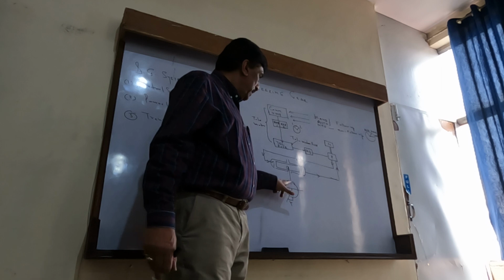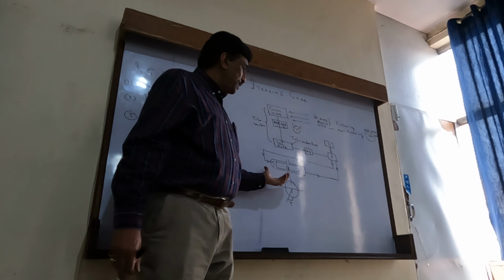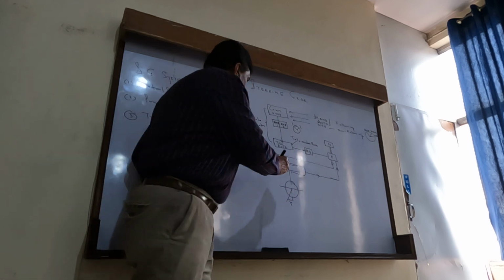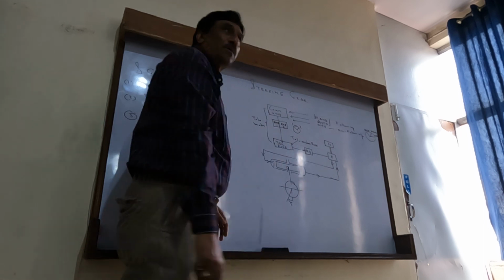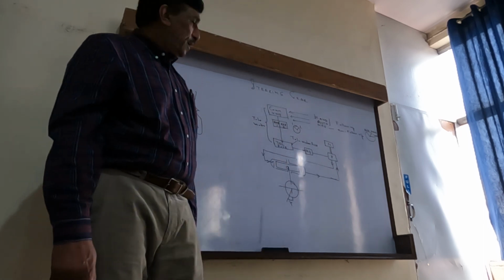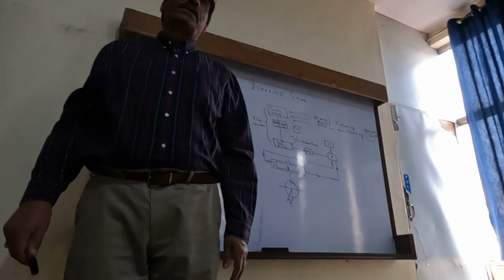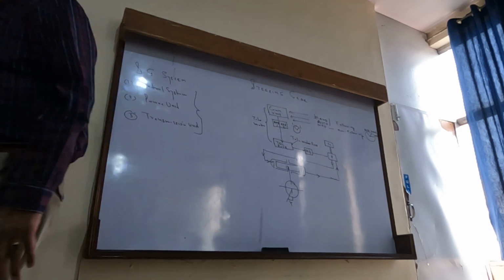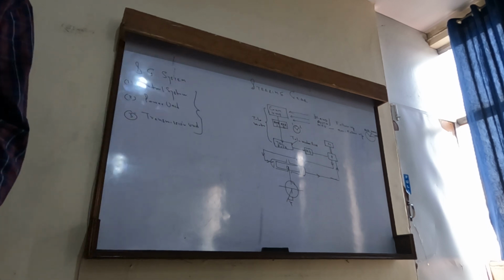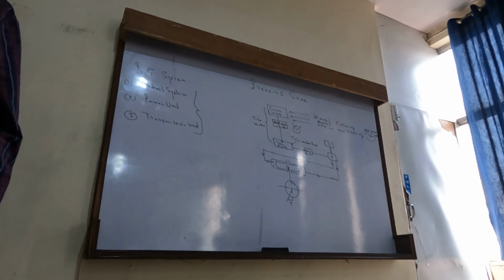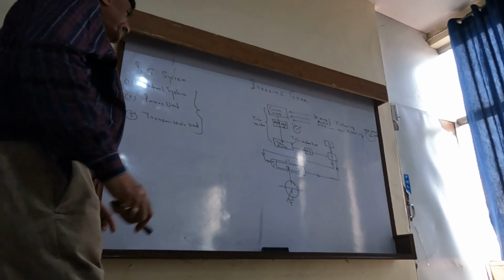So now this is what is causing the movement. This is my power unit and this is my actuator. When it moves from this to right, this is causing the rudder stock to also have angular movement, and because of that the rudder moves from here to this way, port side. Whatever alpha is the angle, this may be midship to 35 degrees. My normal range of steering gear is 35 from one side to 35 on the other side. So in between I can give any movement.